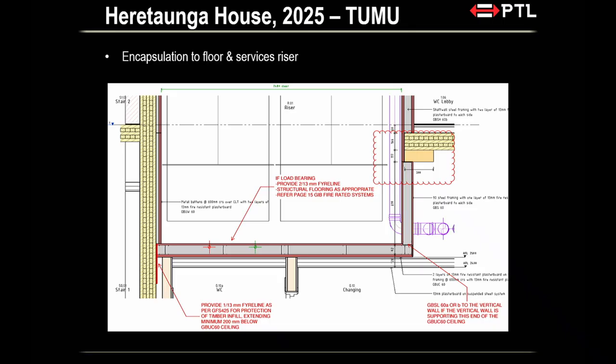There's the usual coordination of fire stuff, doing a bulkhead. So by the way, this is a section of the riser, right? You're looking at the section of the riser, services coming through here and going up. We have to build a bit of a fire rated wall and then jib shaft wall system all around, going up.